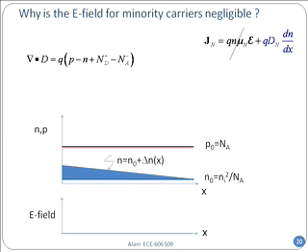So you remember that in the middle section, light was shining, it generated electron-hole pairs, G multiplied by tau sub n, that was the extra carriers, and it was sort of coming out into region 1 and region 2, the two contact sides. Let me assume that it was coming out with a linear profile in the trap-free region.